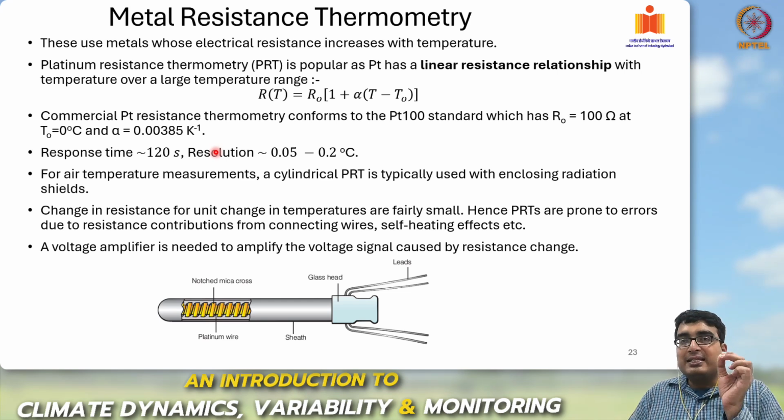So the response is quite small. The resistance change response is quite small, so you have to have a good amplifier to amplify that response properly without inaccuracies. Okay.